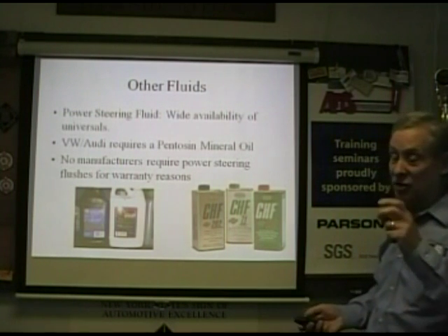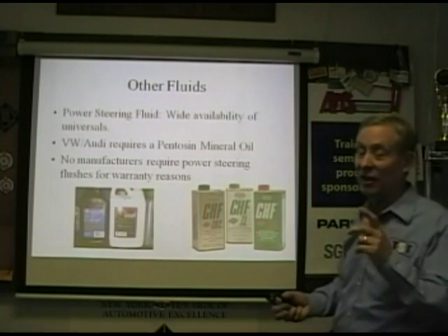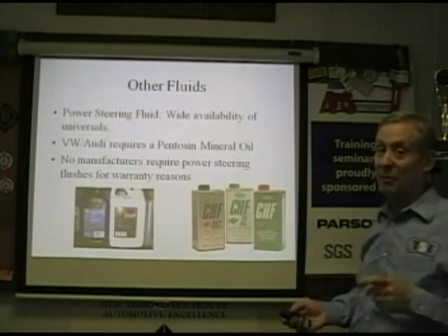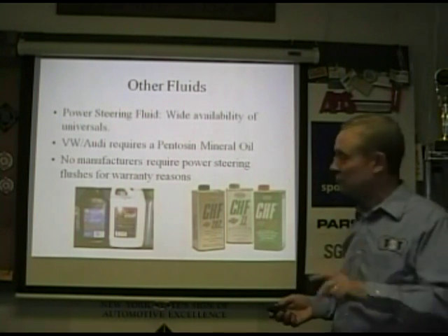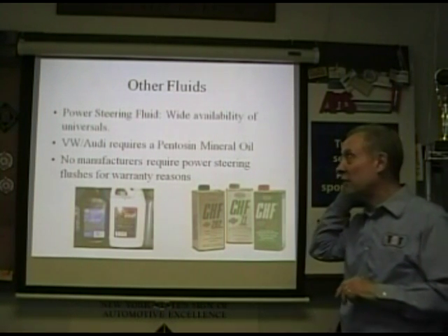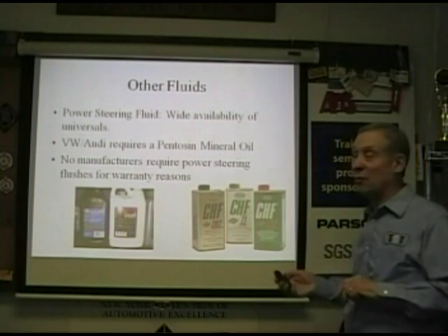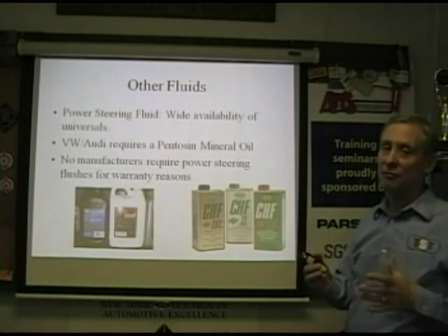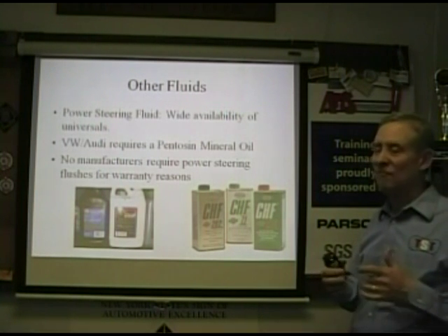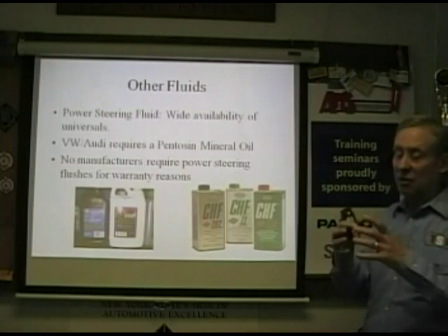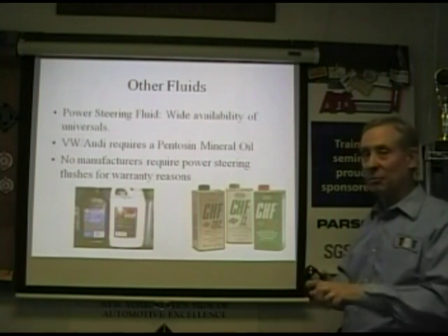The early ones were CHF 7.1. The later ones are the synthetic 11S. You got to make sure you got the right one. They're both green. No manufacturers require power steering flushes for warranty reasons. However, just be aware, most manufacturers today have a filter that's replaceable in some form in their power steering, and there's no real stated interval for most of them. Sometimes it's the whole canister, sometimes it's a replaceable filter.